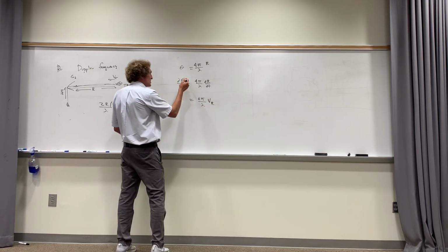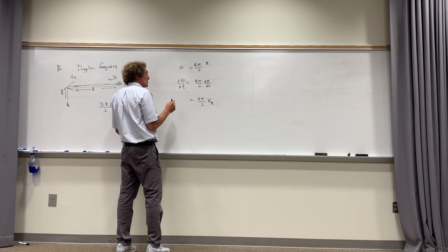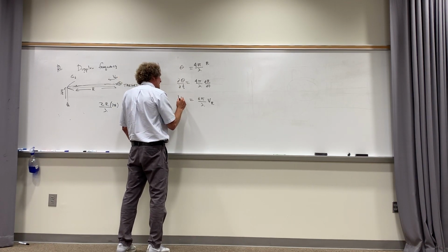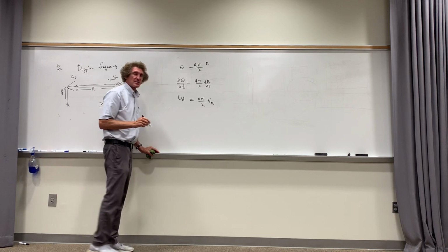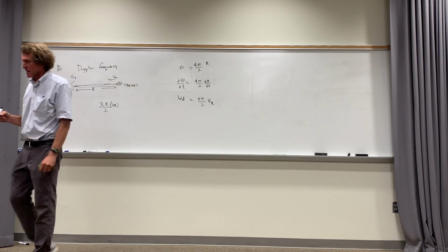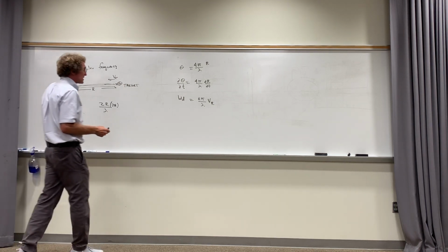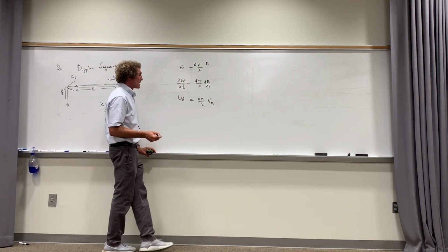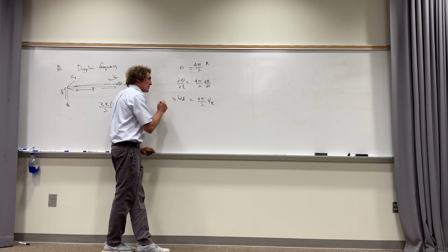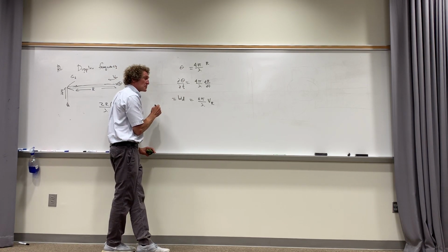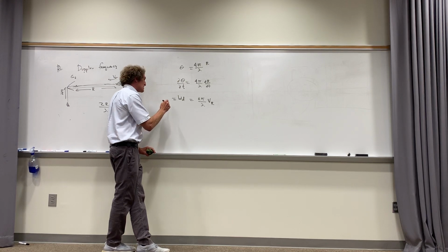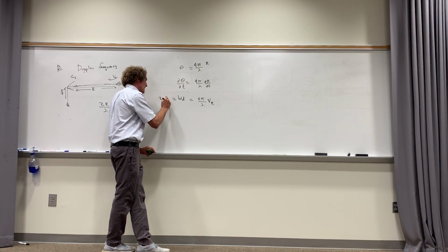And that's equal to the rate of change of theta with respect to t, or omega, and put a sub d there. The d means it's a Doppler frequency. This frequency is something associated with the rate of change of the distance, or the velocity. Well, the Doppler frequency in radians can also be interpreted as Doppler frequency in hertz, and that's 2 pi times f Doppler.